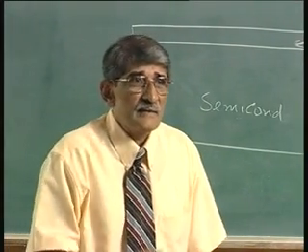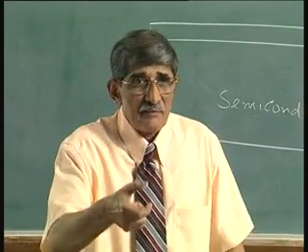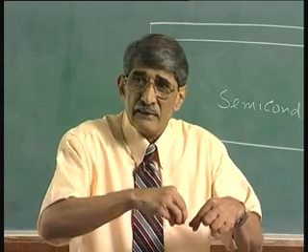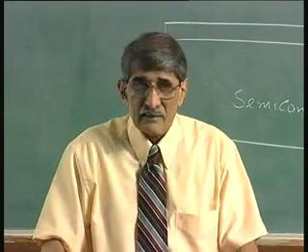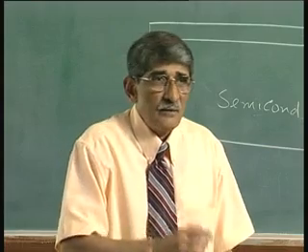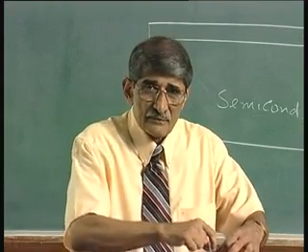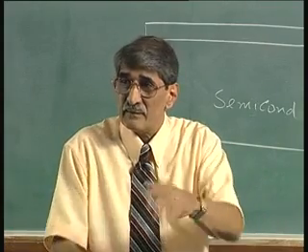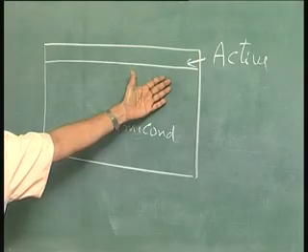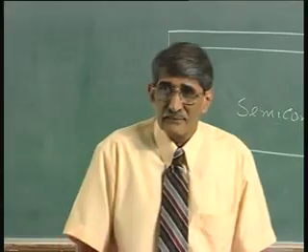The harmful things that it does are some of the capacitances which come from the device to the substrate, and also the capacitance when you interconnect the devices, the capacitance of the interconnection layer, or routing capacitance, whatever you want to call it, with respect to the substrate. That also comes up here.